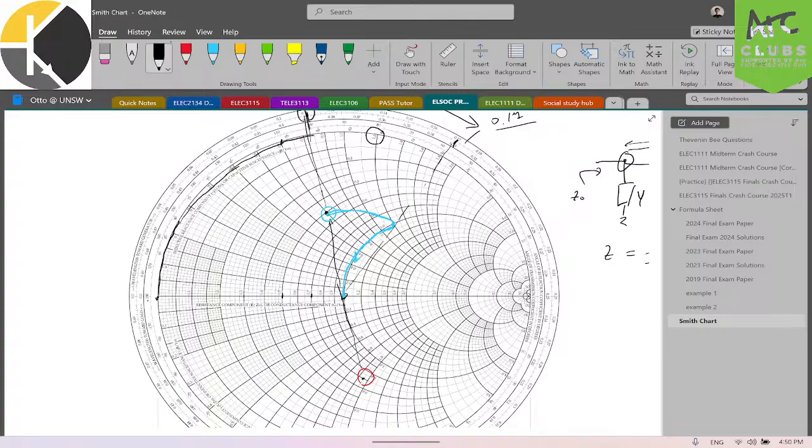Another question. Yeah. Isn't short circuit on the right-hand side? Short circuit is, in this chart, on the right because I should probably draw in different colors. The blue graph is for conductance mode. So for blue lines, the left-hand side would be open and the right-hand side would be shorted, because you are using a single-sided Smith chart and you have to work in both conductances and impedances, because you could add shorted stubs either in series or in parallel. So you have to be able to work with both.